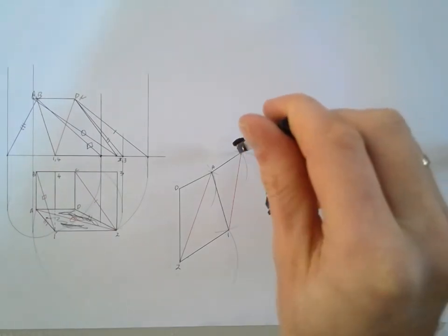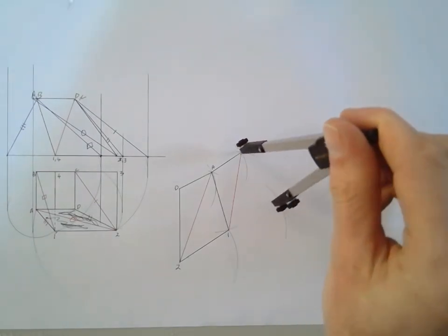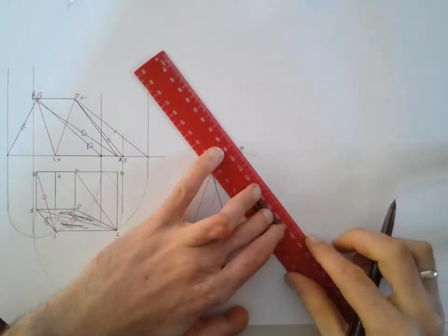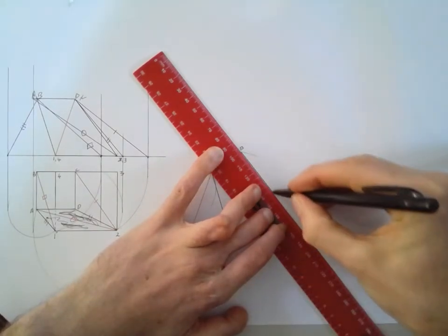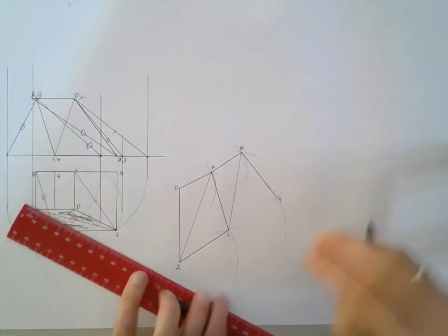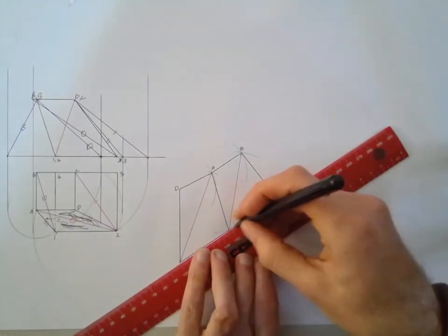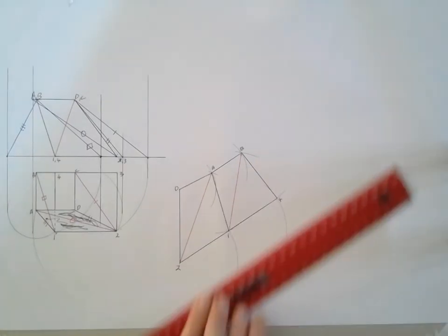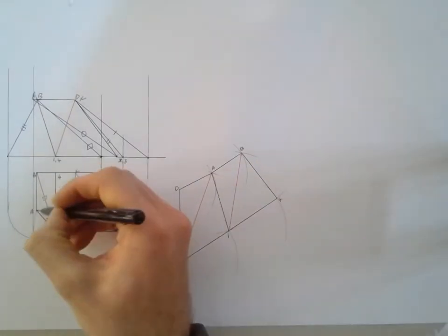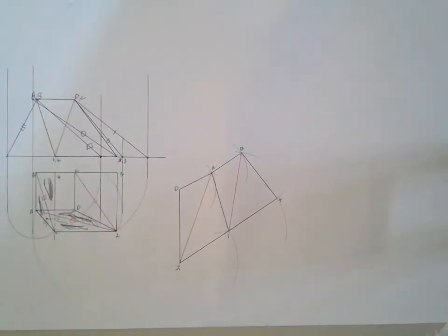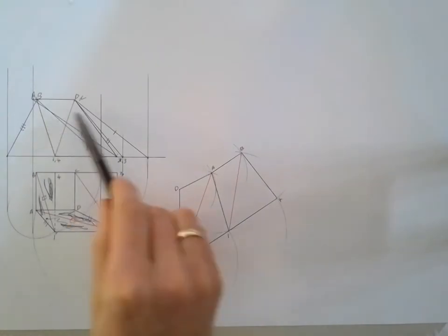Okay, so because we're drawing line B4, place it on point B, make an arc, and when those two come together, you've now got line B4 over here. That's now point 4, and then you have the baseline 4-1 or 1-4. That now completes this triangle and that triangle, which was for the surface facing away from you. Now you go to the vertical face at the back. That vertical face at the back, you've got two triangles which you've created in the front view here.